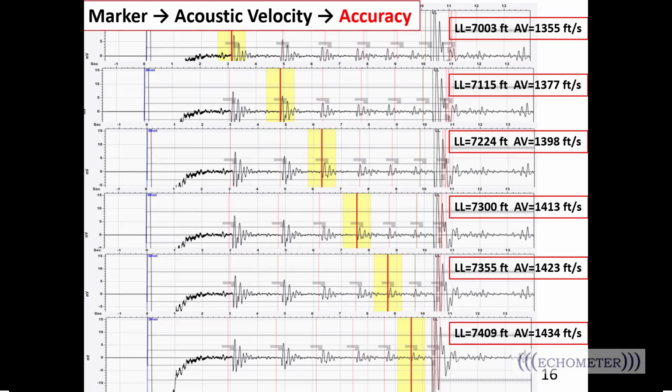Well, Lupe has a question, kind of a common question, and many users are asking, does the amount of pressure in the shot or pressurizing the gun make a difference on the velocity? No, more pressure makes bigger echoes. So when you charge a gun to as high pressure as possible, let's say you have the remote fire gas gun, and the maximum pressure you can have in that gun is 1,500 pounds of pressure, and let's say the casing pressure is 700 psi. So you've got about 800 psi differential pressure. That's going to make the echoes as big as it can possibly be with the remote fire gas gun.